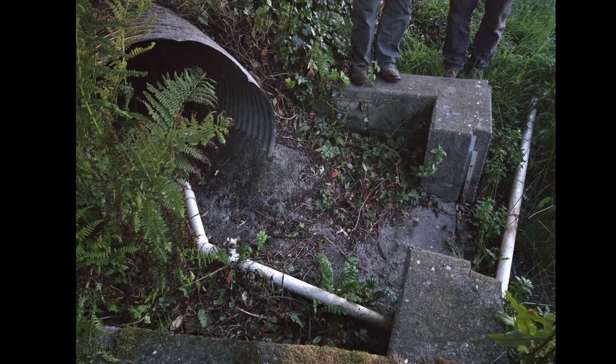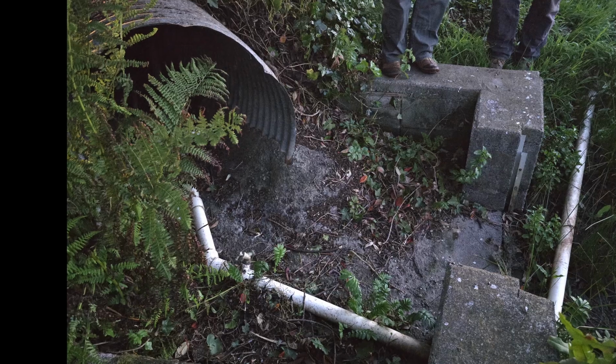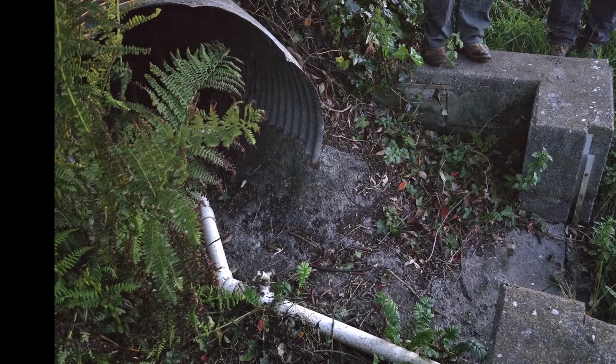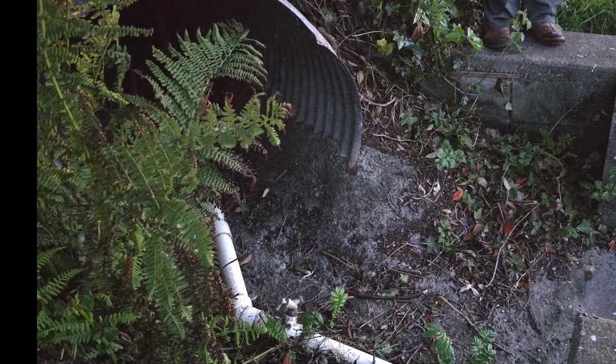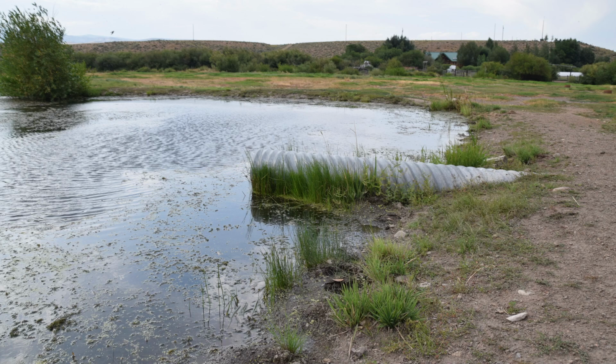An irrigation pipe was installed in front of the structure and in front of the culvert. Both the water control structure and the irrigation pipe are reducing the capacity of the culvert to carry water during a flood, and this could cause the water to flow over the dam. The soil covering this overflow pipe could wash out in the next flood unless livestock are kept off the dam and the spillway is constructed to handle overflow from the pond.